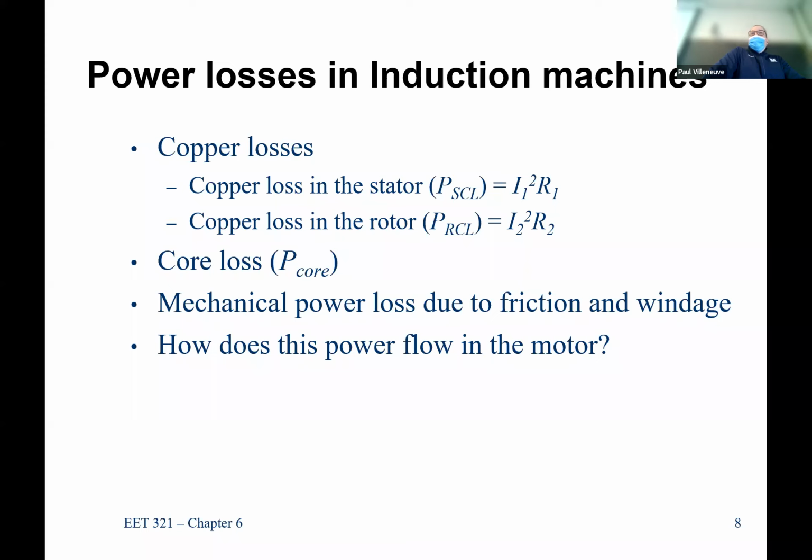a little bit, but it's not so hard like you would with stones. And you can get them to be soft so that you can just run them around, and over time they will smooth things out because the bearings themselves aren't directional and the walnut shells aren't directional. So you can get very, very smooth operation. So that's how you polish or smooth bearings. If you're really into cars, you can actually do things with polishing.